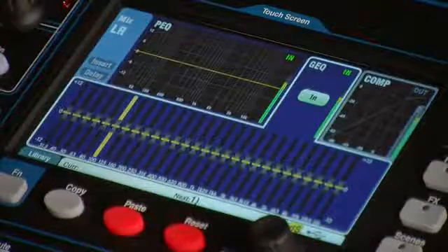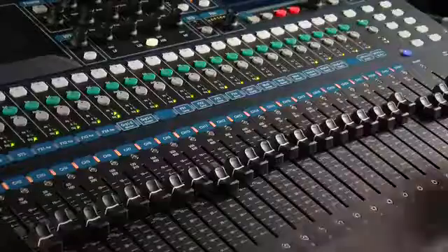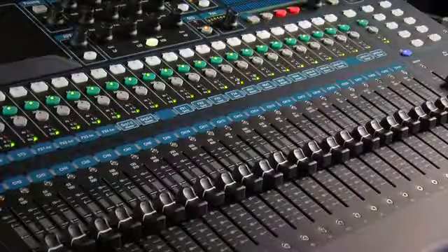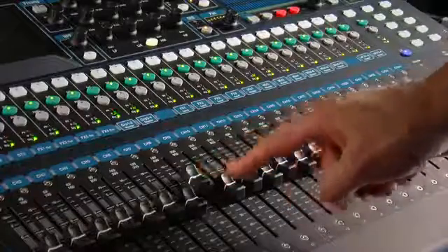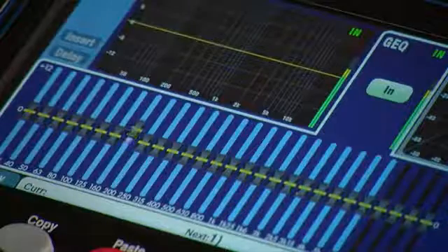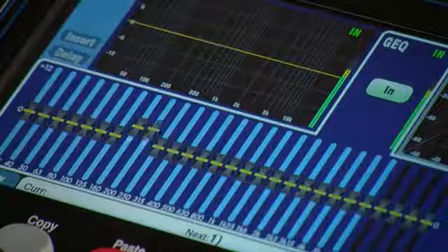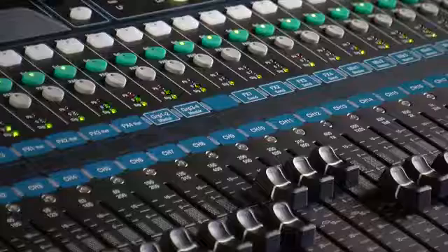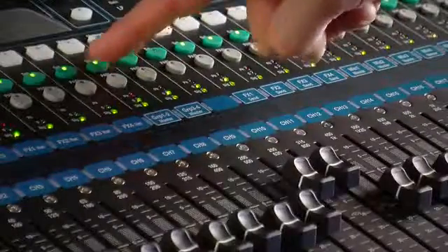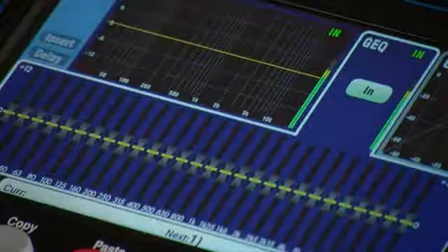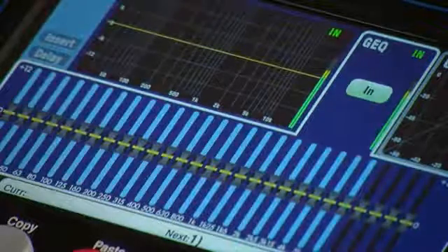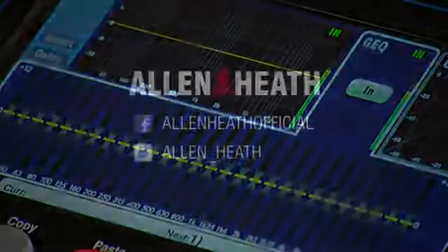Touch a slider to highlight it and use the screen rotary to cut or boost its frequency, or press the GEQ fader flip key to view and adjust the GEQ on the faders. The frequencies are shown on the screen and marked on the panel above the faders. The fader strip select key returns the slider to 0 dB. Press GEQ fader flip again to change range or return to normal mix mode.